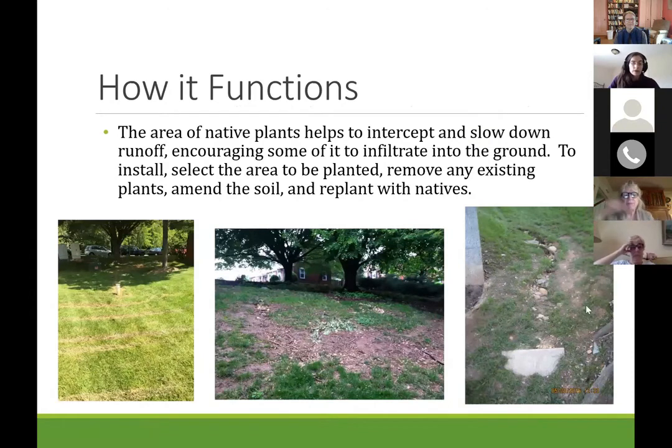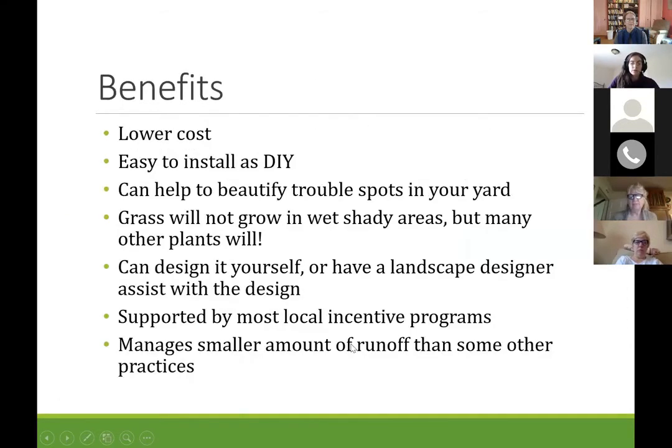Conservation landscaping, so again, using the native plants, we're trying to just improve the infiltration of the ground, getting deeper rooted vegetation than the turf. So hopefully if there's some storm water moving through there, more of what falls on it is going to soak into the ground rather than running off the turf. A lot of water on a turf, especially with the slope, is going to be conveyed across that landscape. It's not going to really have a chance to soak in. So we're hoping with the use of these native plants to give an opportunity for the water to